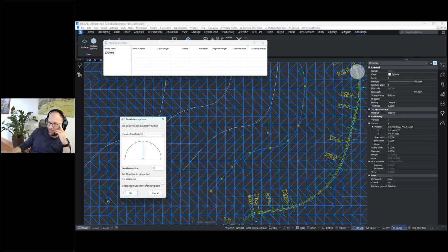As you know, we don't have any arcs in 3D, so arcs are only possible to draw in a 2D plane. So we need to segment those arcs for the 3D polylines. We can do this using this command here. So we actually define the distance between the arc and the 3D polyline.